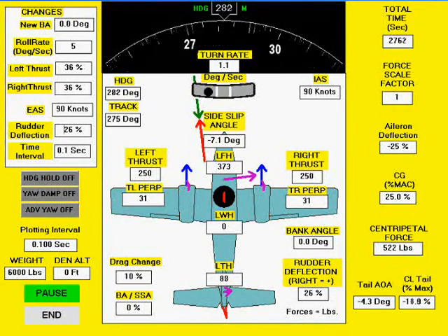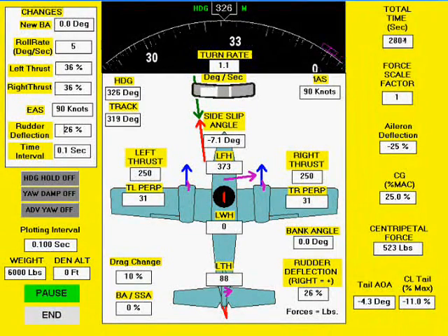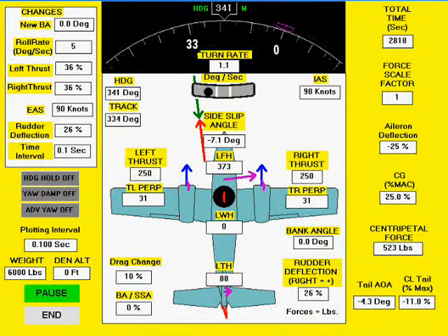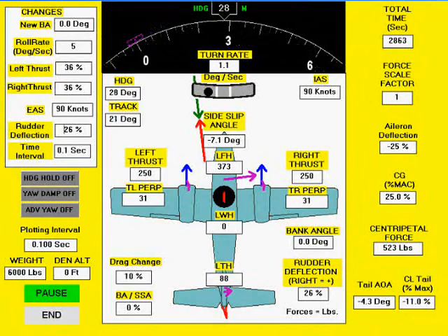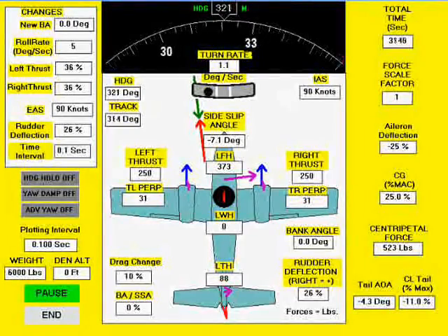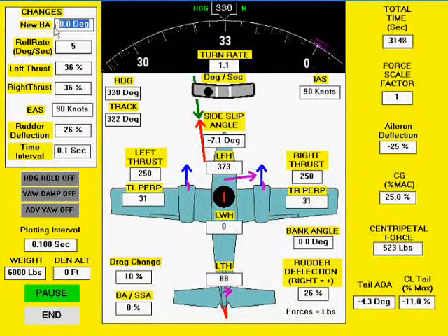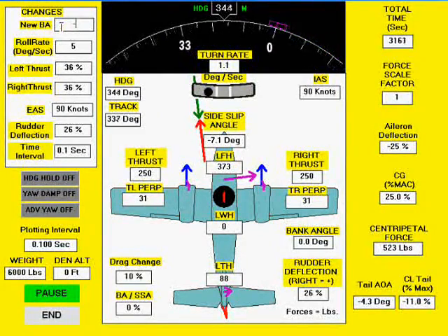This produces fuselage lift, which is perpendicular to the relative wind. Think of the fuselage as a thick symmetrical wing with a very short span turned on its side. The combination of fuselage lift, tail lift, and horizontal components of thrust provide the centripetal force that creates the turn. Note that this centripetal force is approximately the same as the value created by a 5-degree bank angle and produces the same rate of turn. So, what will happen if we now apply a 5-degree bank angle in the opposite direction?